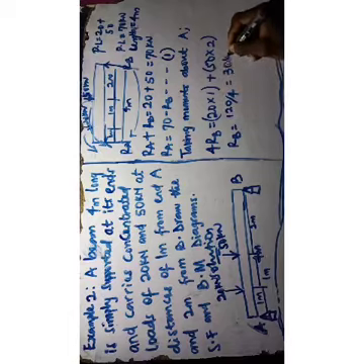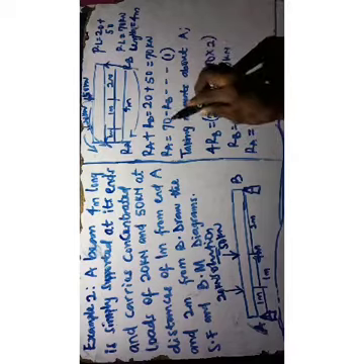30 kilonewton. That is your RB. Now you can get your RA. That will equal 70 minus RB. That is 70 minus 30. That equals 40 kilonewton. So in this state here, we've gotten the reaction at both ends. So we can therefore get our shear force and bending moment for the ordinary simply supported diagram.